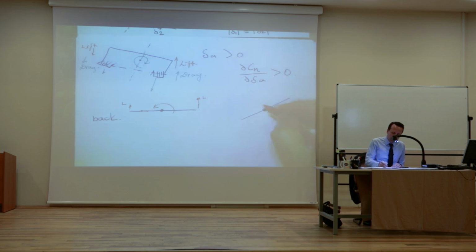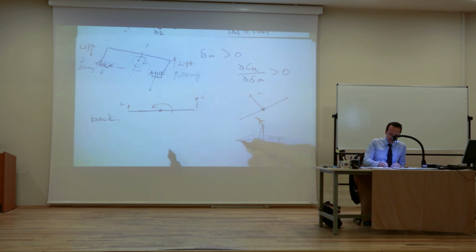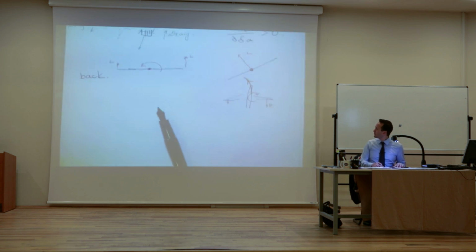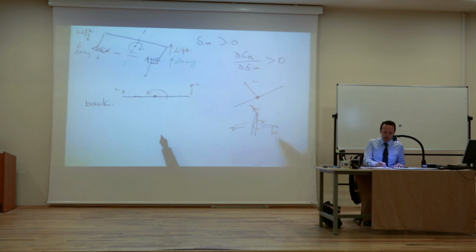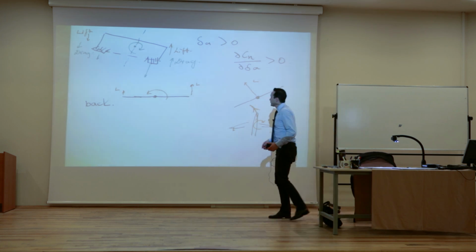And because of that, what I just explained to you, this will now be your total lift, and you really want to turn, looking from the top. Looks like you will be turning in this direction, like that, right? This is your rotation. However, look at the drag. The drag is more over here and less over here, and it actually tries to rotate you in the opposite direction, you see? It's actually not a good thing. You understand what I'm saying? Let me try to explain it to you again.